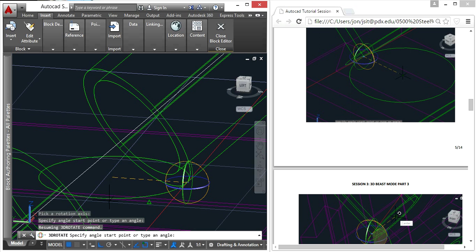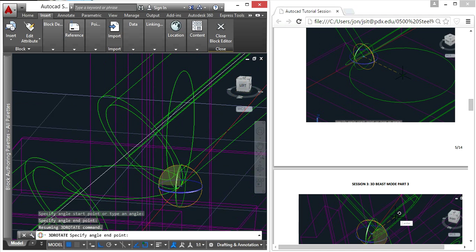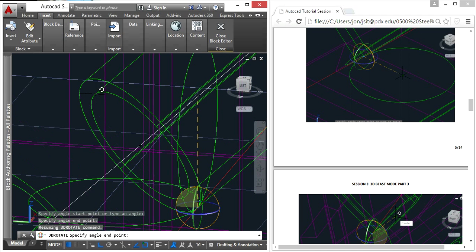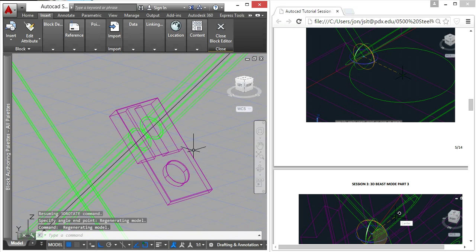Let's try to see if we can get a center. And if you can't get a center, if you have ortho on, just click somewhere, and then click on something else that you can grab. So could be that quadrant. If you click, it'll make it perpendicular. Alright?